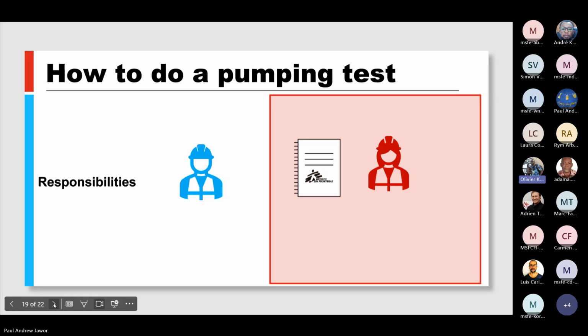If the pumping is 6 hours, we should ensure that the pump runs for 6 hours continuously. If there is any interference and we stop, we should allow a pause so that the water level rises back to the static water level before we start any pumping event again. Generally, we would recommend 12 to 24 hours.